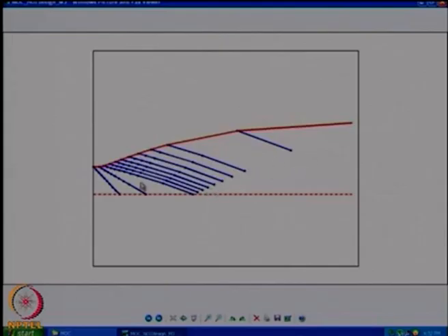And so here, after this point I did not plot, because that is the end of my nozzle. After that if I plot, they will just be parallel lines going all the way straight to the axis, and from there each of these points will just go back out parallel, and all the Mach angles after this last line will be the same as my exit Mach angle, which for Mach 3 will be sin inverse 1 by 3. That is what you will get here.